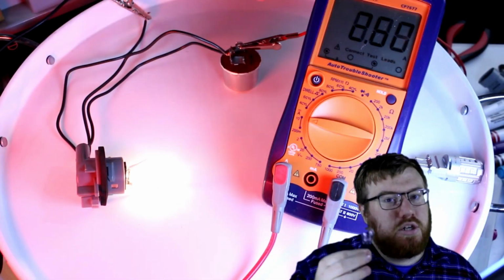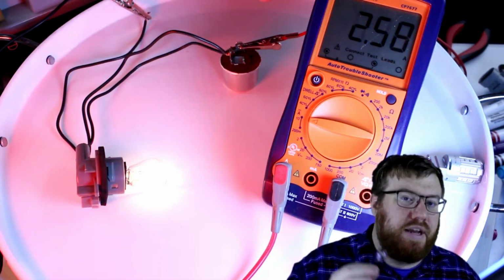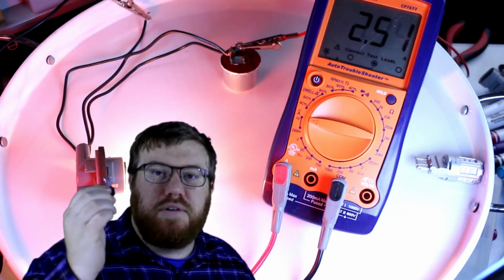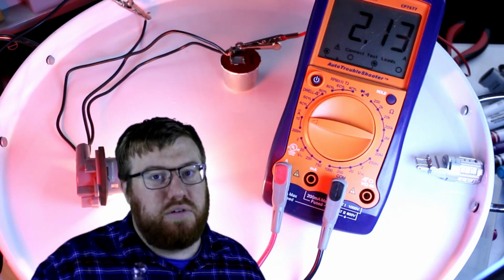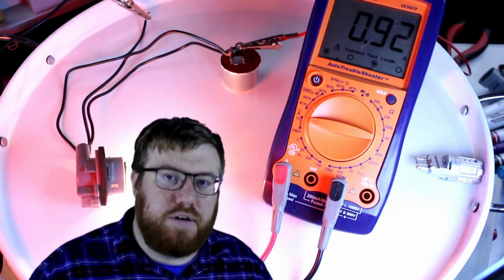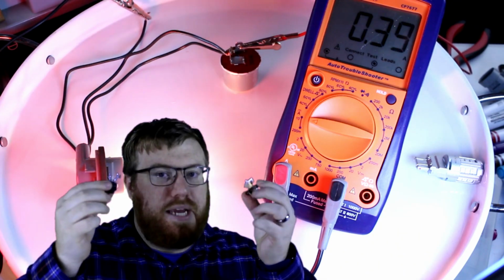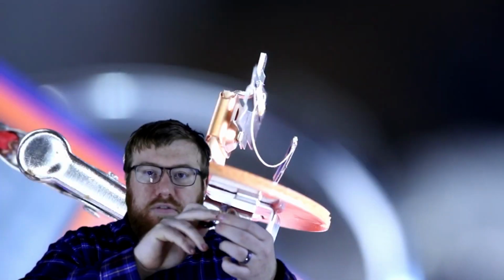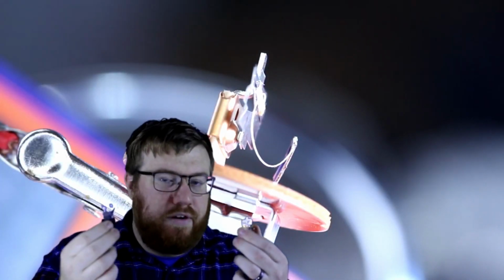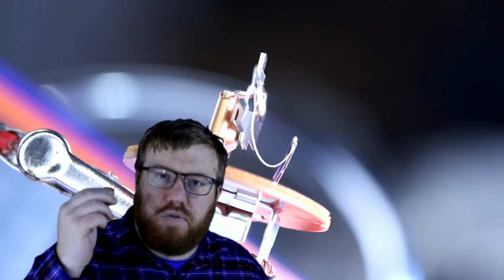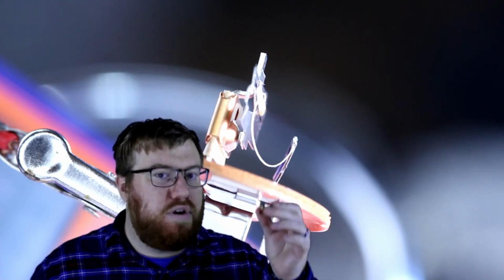While this bulb isn't much of a resistor, it is a resistor. It resists the flow of electricity. It won't stop electricity completely, but it will slow it down in the form of reducing the amperage. These two components are going to be in series, which means electricity flows through one first and then the other. However, turn signals typically aren't just one bulb, and you don't have one of these for every single bulb that you have.